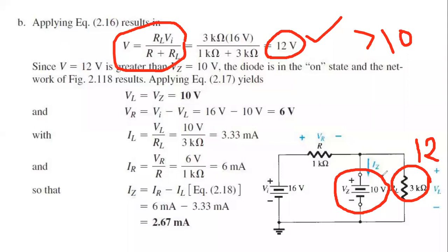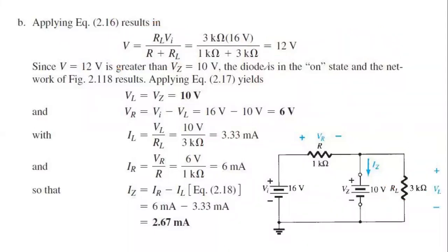A 10 volt source. But my students, a very interesting thing now I will tell you. From the calculations we say that the voltage across this resistance is 12 volt. But when the Zener diode is replaced as the voltage source, the output voltage, or the voltage across RL, will be 10 volt, because those are parallel lines. In parallel lines, the voltage is always the same.